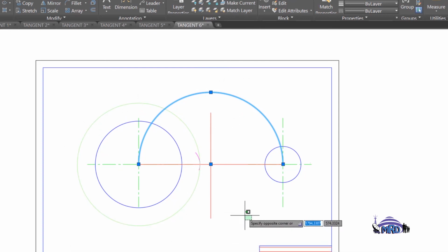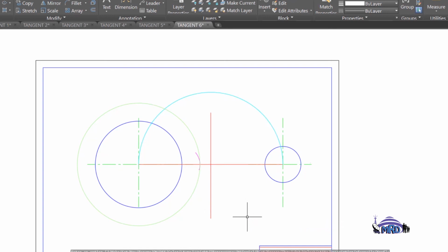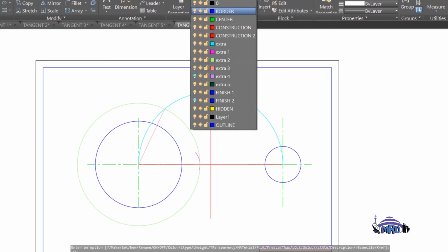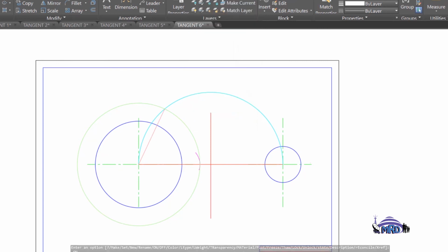We now have to seek to locate the normal for the tangent. So the normal now is a line going from the intersection of the big semicircle and the big circle, from that intersection on the outside that I'm highlighting here, to the center of your original circle. The normal will be coming down that distance, but then you are only concerned with it at this point on the original circle. So if I drop in that normal for you now, you would see that line coming all the way through, but in essence you're concerned with the intersection right here on the blue circle,